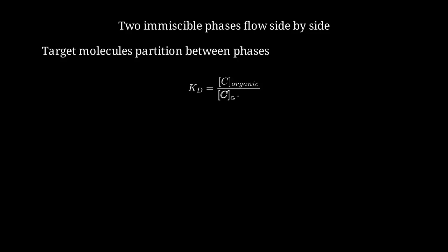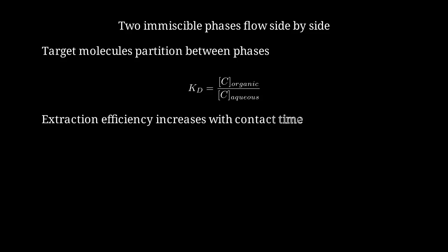The partition coefficient Kd equals the concentration in the organic phase, divided by the concentration in the aqueous phase. Extraction efficiency increases with contact time and interfacial area, both of which are optimized in microfluidic devices.